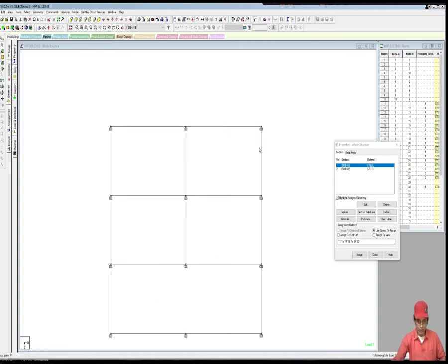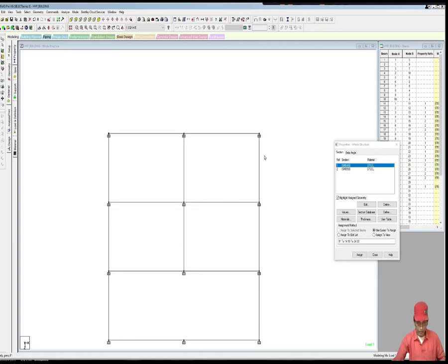So we need to have a secondary girder to support the stringer beam. So this should be around 1.35 meter plus 3 meter plus 0.45 meter.